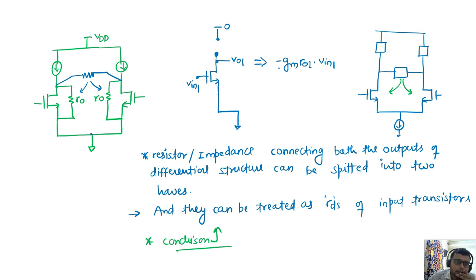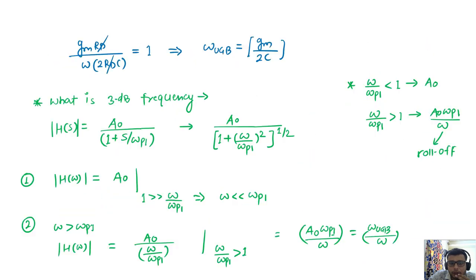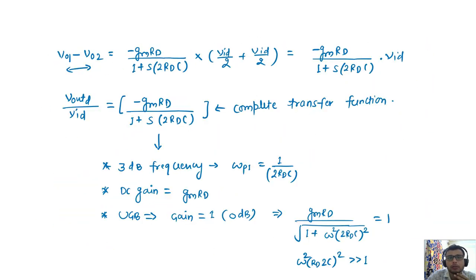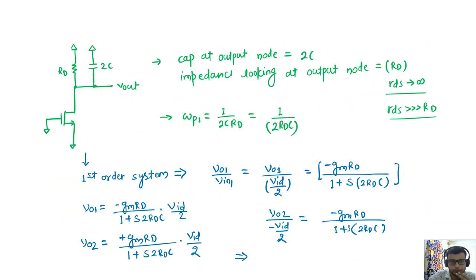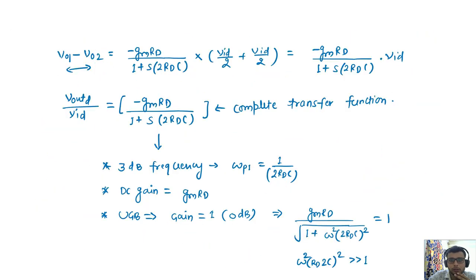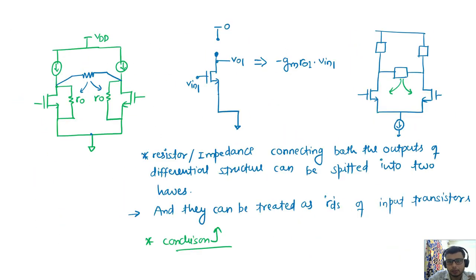What other thing can I discuss about this circuit? I think these things are clear. I also asked about the zero, but there is no zero. We see a zero in some other structure where there is a direct connection between input and output, then a zero can be there. In this structure we can see this capacitor was here, so there is no direct input to output connection, or I can say at infinite it can happen like this.